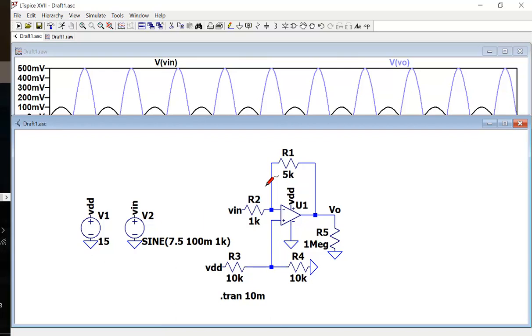When you are connecting on the breadboard, you have to use a little screwdriver to twist it and probe it at the same time until you see exactly 7.5 on the multimeter's monitor, and then you stop. Okay, this must be 7.5. You cannot just put a potentiometer there and assume it's going to work. No, it won't work. This must be 7.5 volts.